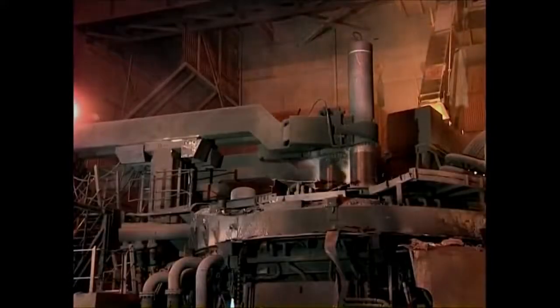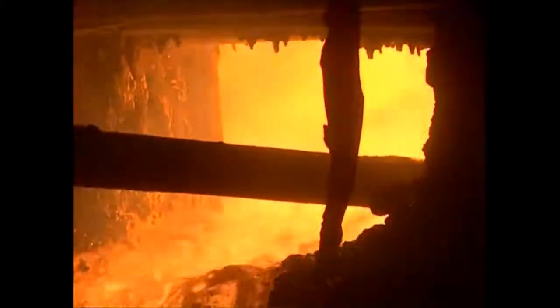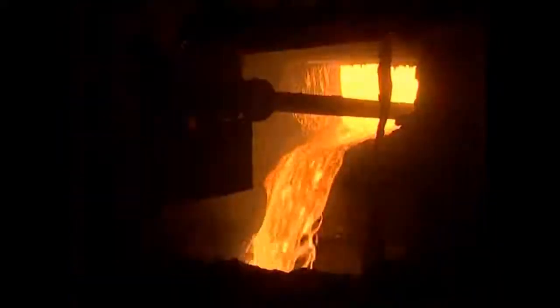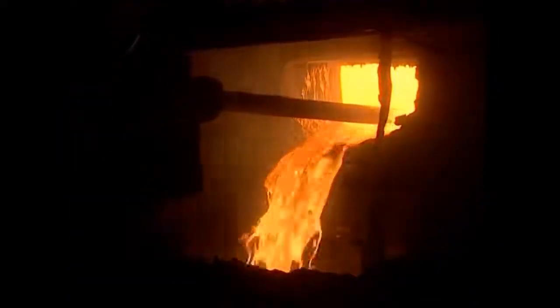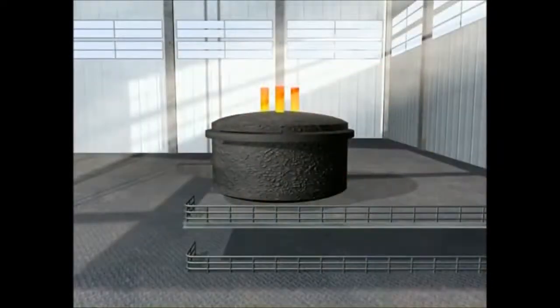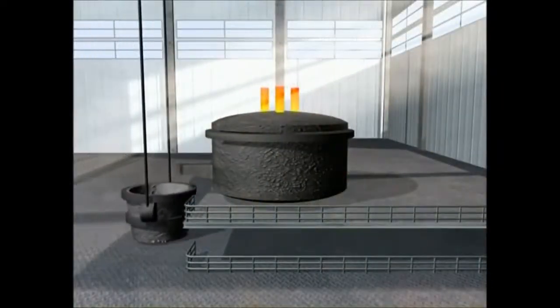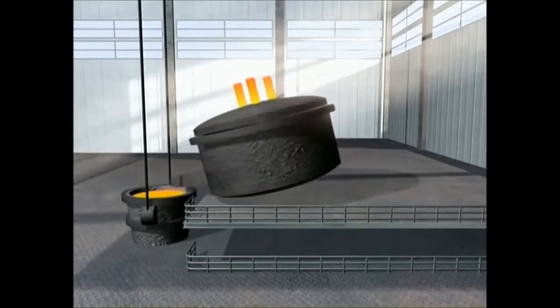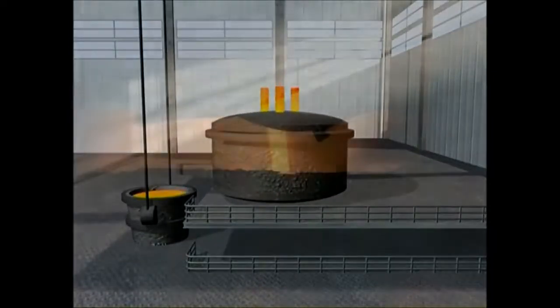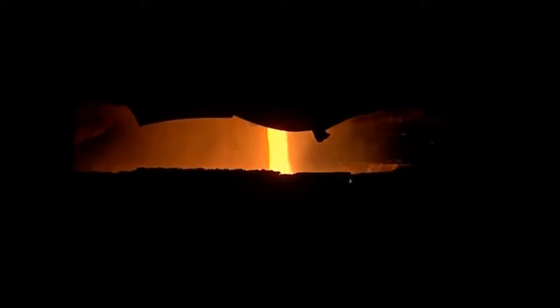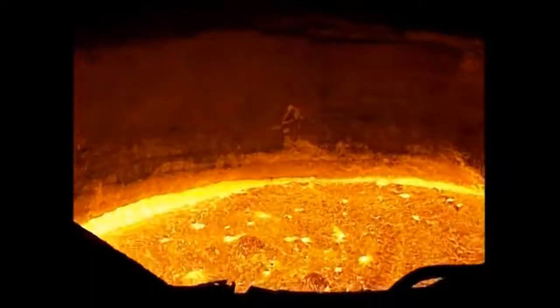Lime and fluorspar are added and usually carbon and oxygen are blown into the melt. As a result, impurities in the metal combine to form a slag. The steel is sampled and analysed, and once it reaches its correct temperature and composition, it is tapped off. At this stage, final adjustments to precise customer specifications can be made by adding alloying elements. These furnaces give very precise control over composition and are used for producing a variety of special steels, including alloy steels and stainless steels.